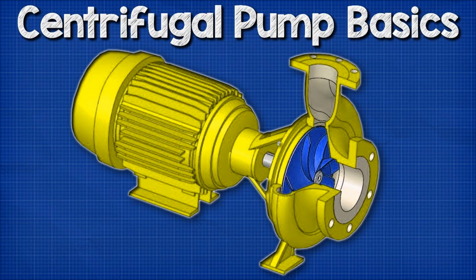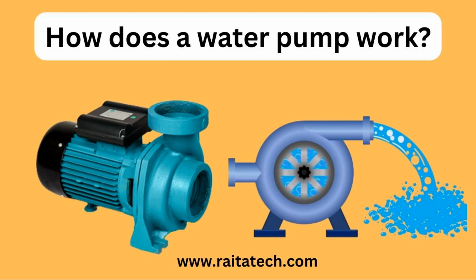Impeller. The impeller is a rotating component with curved blades that accelerates the fluid. It is typically mounted on a shaft. Casing/volute. The casing or volute is a curved, spiral-shaped housing that surrounds the impeller. It helps in converting kinetic energy into pressure energy. Shaft. The shaft connects the motor or driver to the impeller. It transmits the rotational energy from the motor to the impeller.